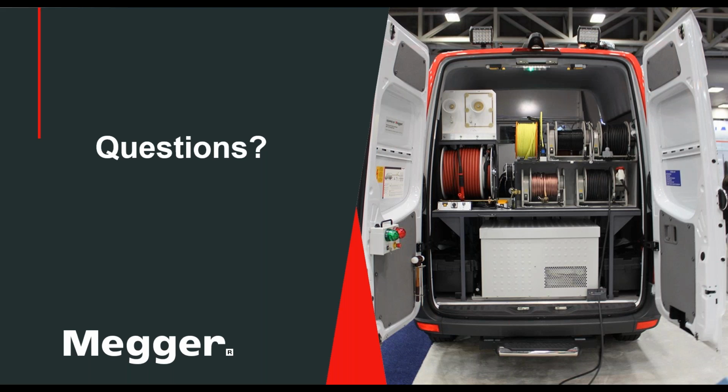Your next question, Henning, is could you please provide an example of a voltage that would be used for breakdown tests for a 35 kV cable? Well, it's basically the same as what we just talked about. When you run a breakdown test, you're not using a defined voltage. You're using the voltage capability of the unit to run it basically all the way up. So in this mode, you would set the highest voltage you have on the unit. In the case of the ST25, you have 30 kV, you punch in 30 kV and you turn it on.